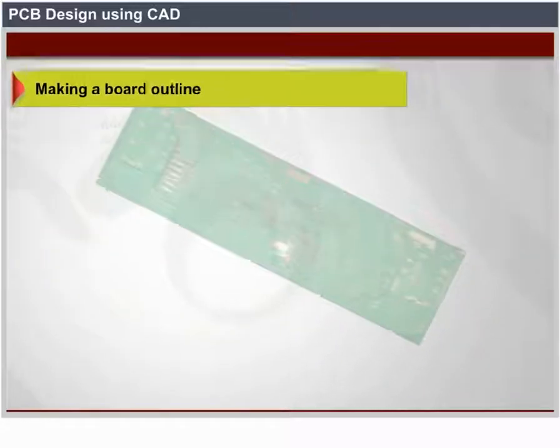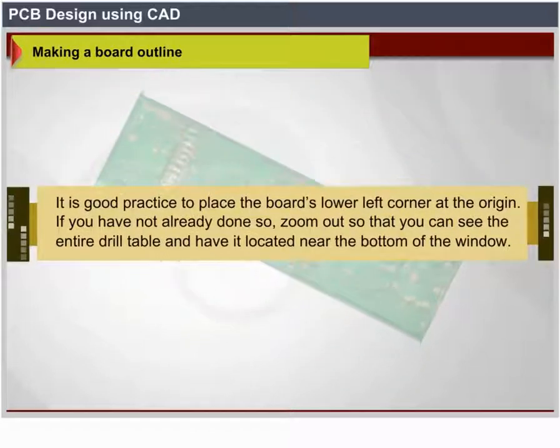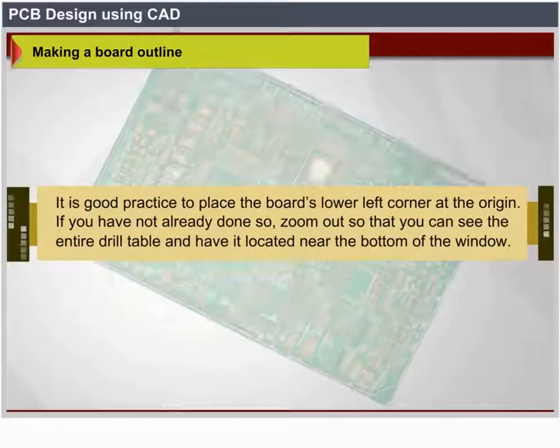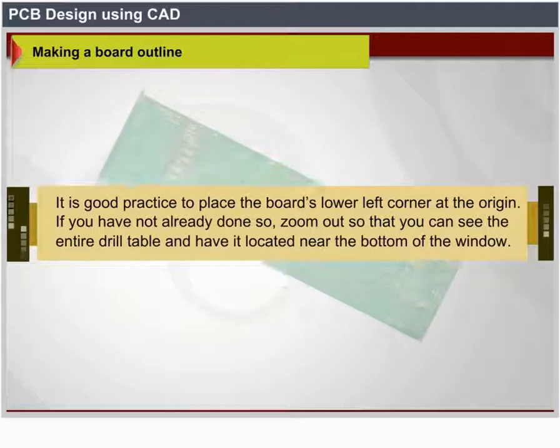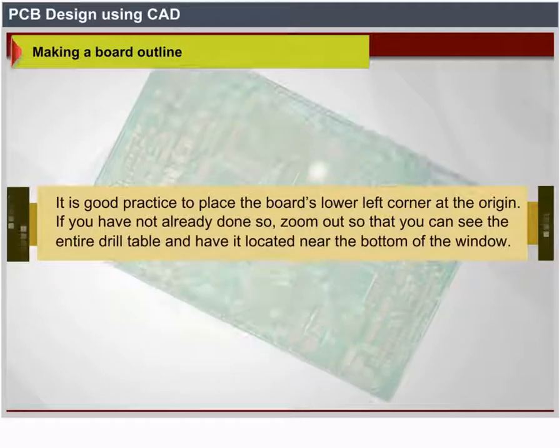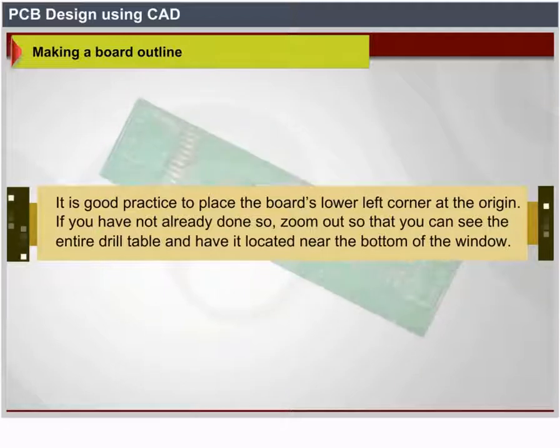Making a board outline. It is good practice to place the board's lower left corner at the origin. If you have not already done so, zoom out so that you can see the entire drill table and have it located near the bottom of the window.